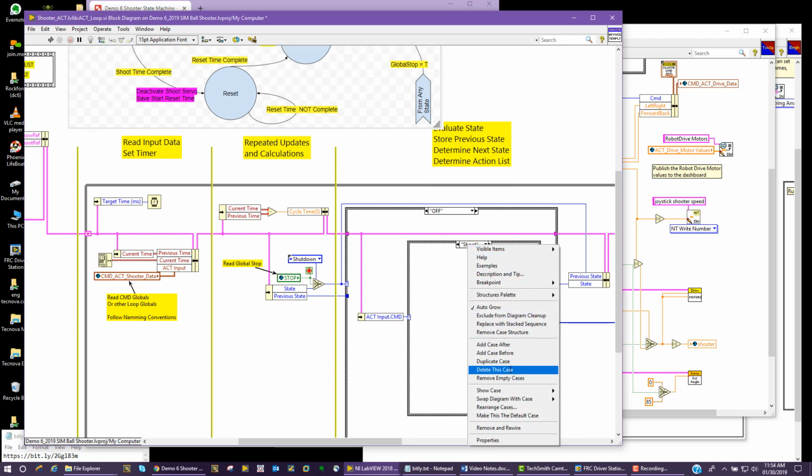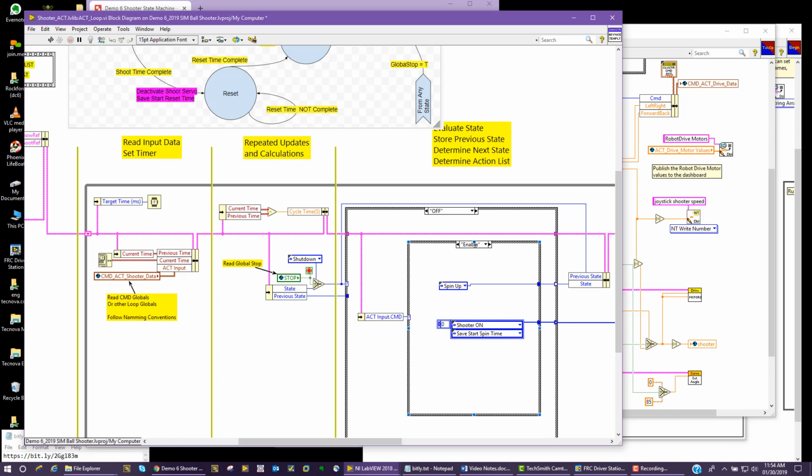The code for enable and shoot are identical, so you can actually add shoot to this case as well. I can put a comma and then start typing shoot, and LabVIEW will fill in the thing that most resembles what is in that enum, and then you can push the arrow keys to fill it in, and we say enable or shoot. For this case, run this code here.